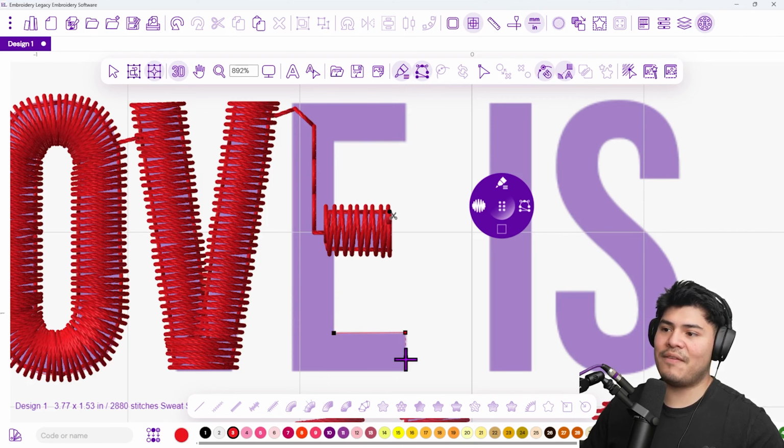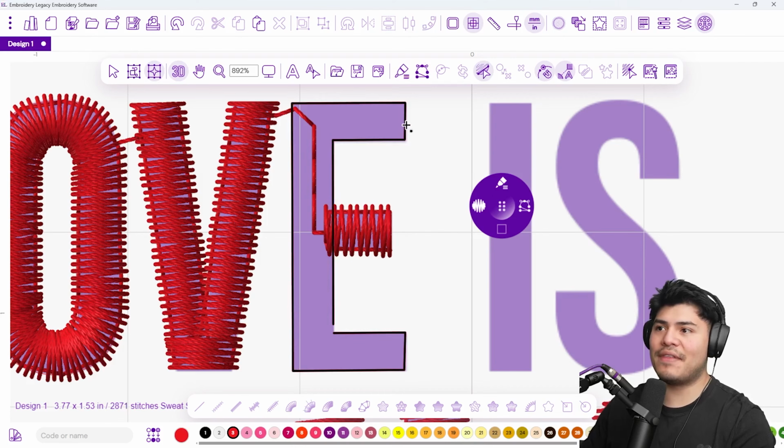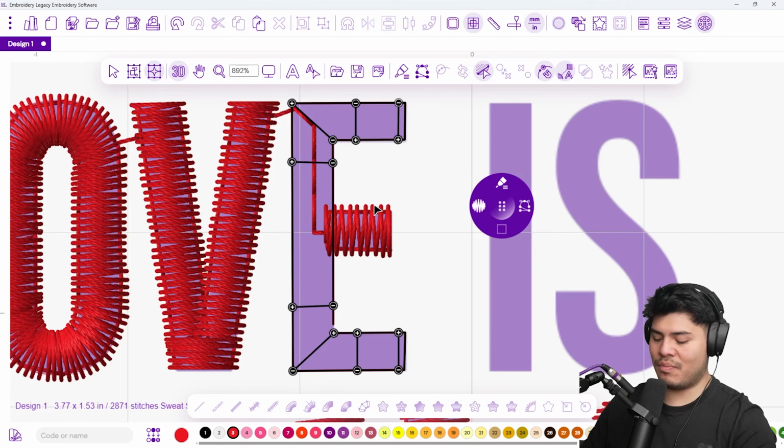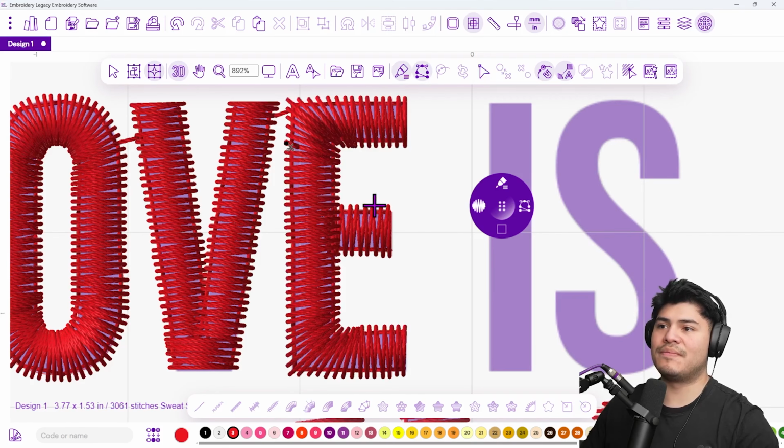So I'm going to press left, left, just to create all of these straight points all the way around, left, left, and let's go all the way back down. Perfect. Now that we have that, let's put our inclinations. So I'm going to make sure that I curve these. Let's put an inclination over here, and let's put an inclination right here. And now we're going to add the ones that are going to help us gradually transition into those curves or those angles. So here I'm going to add a transition. Here I'm going to add a transitioning angle, one more transitioning angle, and one more transitioning angle. Perfect. Enter and enter. There we go.